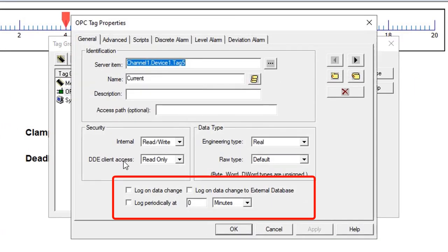While defining a tag, you can also set various data log attributes. There are 3 different alternatives for data logging of a tag. You can use them selectively as needed. You will have to enable and set up Data Logger on the Project Properties dialog.